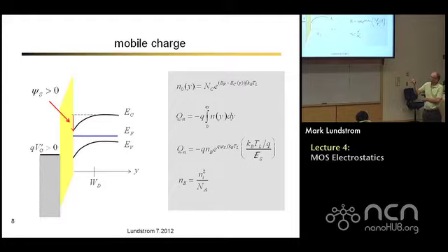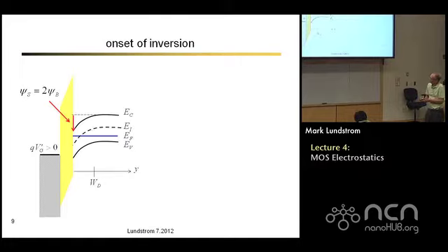That means when the potential drops by kT over Q, the electron density will drop to 1 over e of its surface value, and then I have most of them. The thickness that it takes to do that is the voltage drop kT over Q divided by the electric field at the surface. Okay. So that's an expression, and you know, this is going to be a little fast for one lecture.